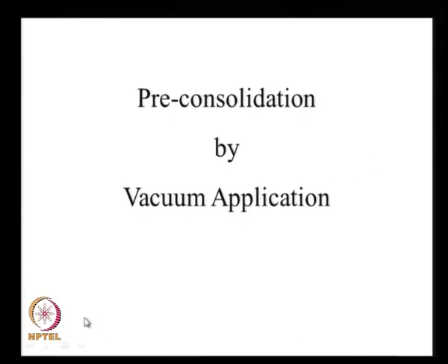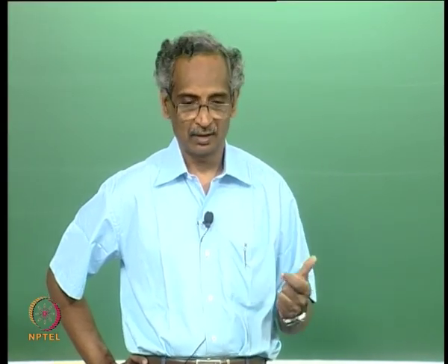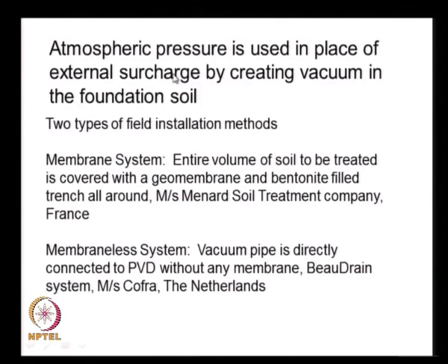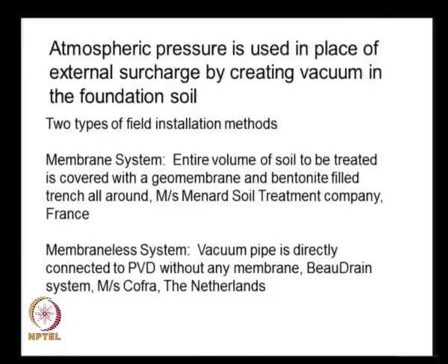And is there a way of achieving even faster consolidation than PVDs and not using a surcharge? That is possible by using a vacuum for driving our consolidation. The principle is very simple. We remove the atmospheric pressure from the volume of clay that needs to be consolidated, and then the atmospheric pressure itself acts like the surcharge, and it drives the consolidation. And as you know, the vacuum is an isotropic stress or an isotropic pressure. So, we get much better consolidation with vacuum treatment.